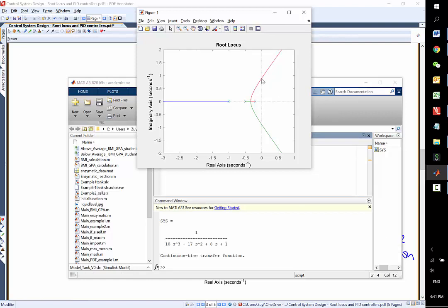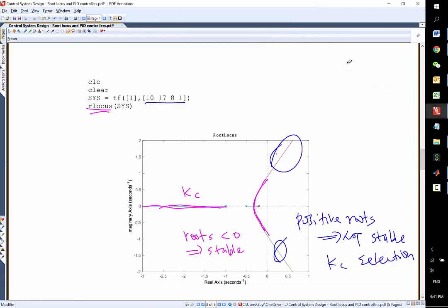And if the gain is larger than this value, then you might get the positive pole, right? So tips, I will not show you to use a gain larger than 12. If for example you get larger than 12, you're going to get a positive pole, and the system is not stable.